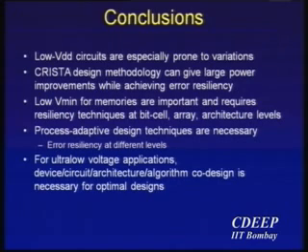One other thing that I didn't talk much about, but mentioned in one of the first slides, is that for very low voltage applications, device, circuit, architecture, and algorithm co-design turns out to be necessary to give you an optimal design. All right, that's all I have. I didn't really look at the voltage generation part, but people have been doing that. I'm not doing voltage scaling during regular operations at all. It's one VDD for all operations. So rather than using 1 volt, I'm using 900 millivolts.